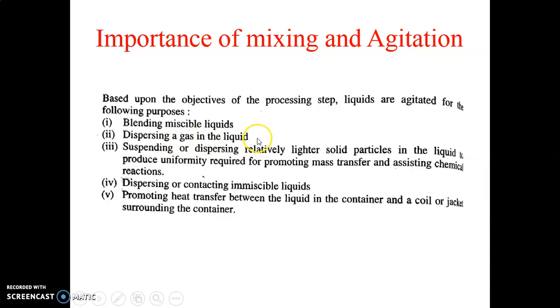Dispersing gas in the liquid. That means we have to suspend a gas in a liquid. At that time we can use the mixing operation. Suspending or dispersing lighter solid particles in the liquid to form the uniformity required for promoting mass transfer and assisting chemical reactions. That means sometimes in mass transfer or in a chemical reaction, we have to suspend lighter solid particles in a liquid. At that time also you can use the mixing operation.